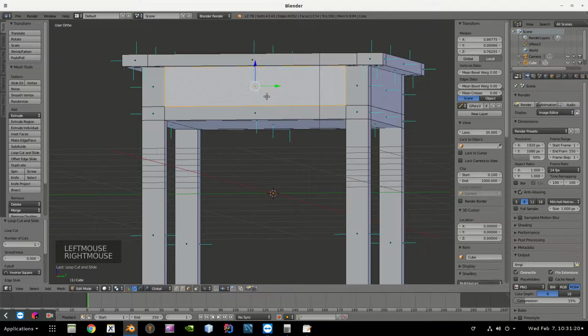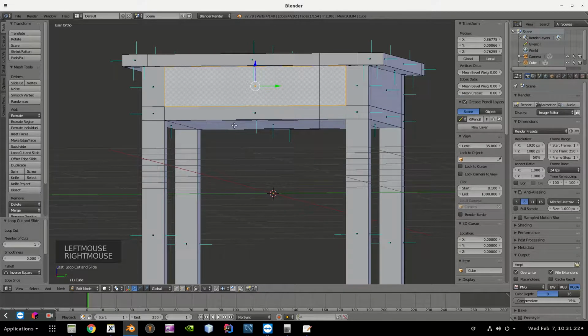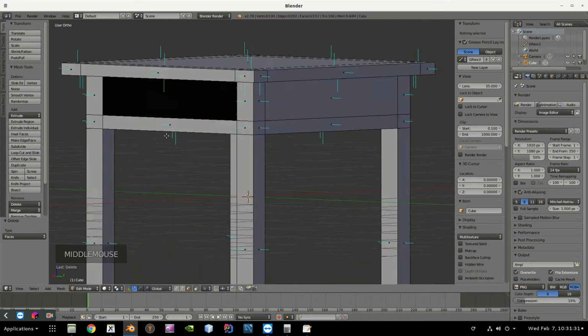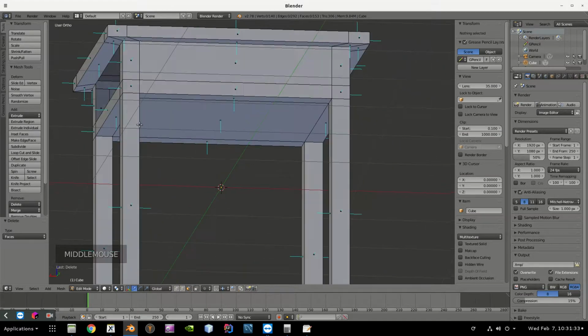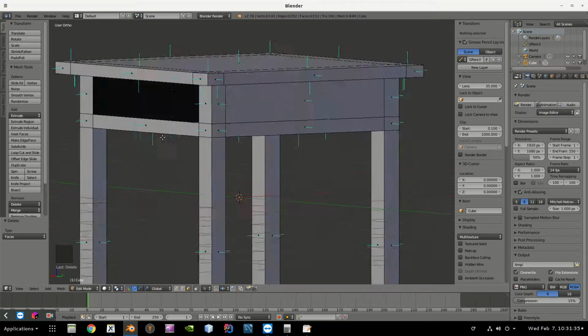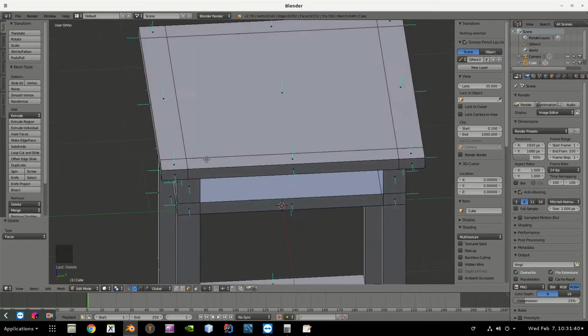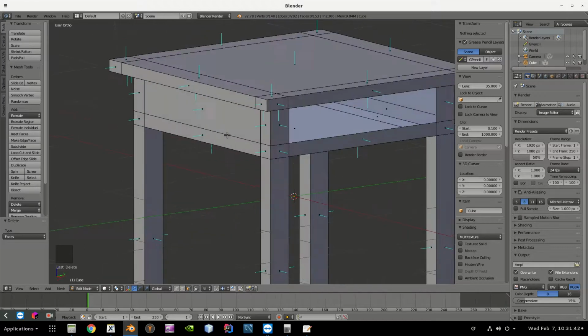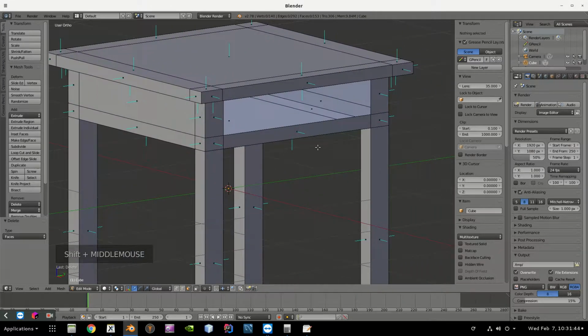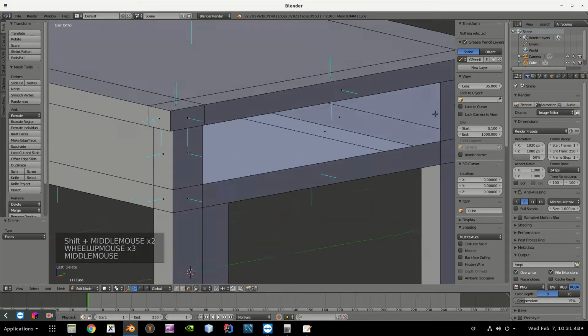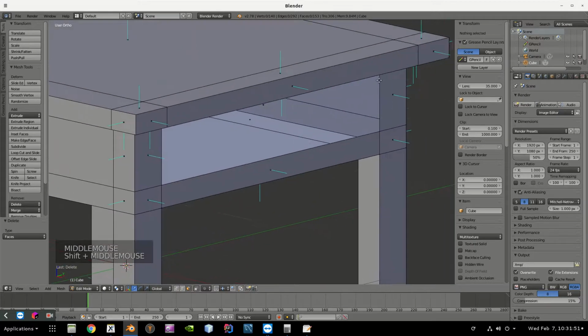What I need to do is I want to get rid of this face. Okay. How do you delete a face? It's simple. Just hit delete and delete the face. So that's that. We have a hollow right in the middle. So this is how it looks like. Now it creates a problem right over here. If you delete the face like that, it creates a problem because, see, we have really thin edges. It looks like paper.